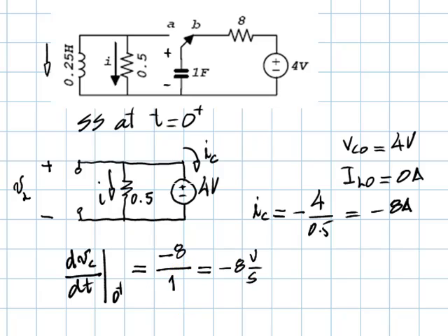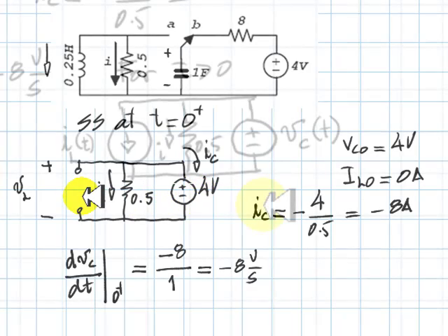However, the initial conditions we're looking for are not in the capacitor or the inductor, but on this resistor according to the exercise. So let's see what is the relationship of that current and the voltage in the capacitor and the current in the inductor. Let's make a drawing of the circuit for any point in time t greater than 0 by considering as unknowns the voltage in the capacitor and the current in the inductor.